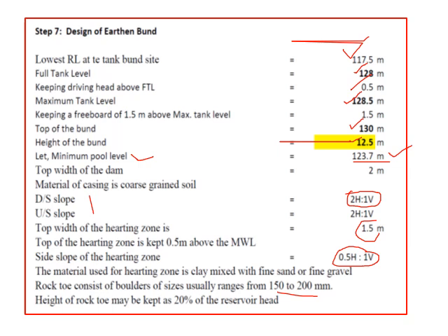So this is how you design the earthen bund. There are a few formulas for fixing the preliminary sections of the earthen bund. You can refer to those preliminary sections, and then decide the top width. Also you can decide the freeboard, and then you can use the slip circle method to decide the slope. You can do a number of trials for the earthen bund and see that you get a safe factor of safety, which will be more than 1.5.